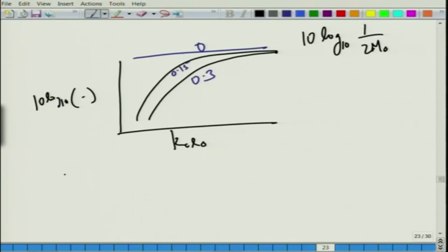So, what basically it would mean is that the interaction of the sound wave and jet, which attenuates the wave as it comes out, amplifies the broadband noise. However, this is sort of inconsequential, because even after amplification the jet noise remains insignificantly low compared to the sound wave. So, now however, what really matters is how the real part of the radiation impedance